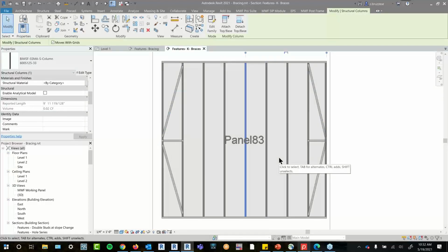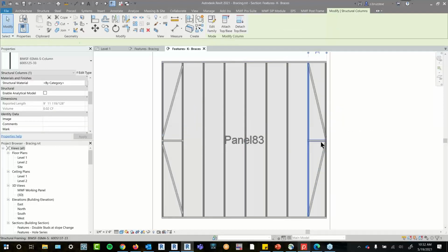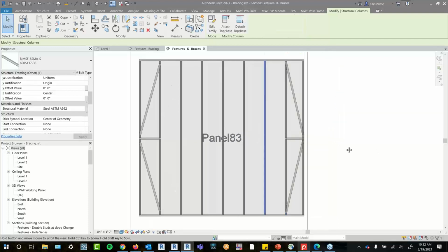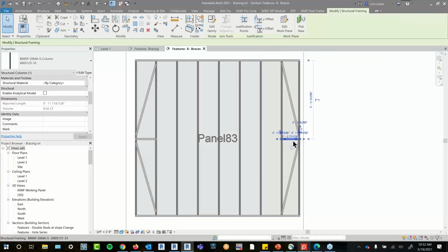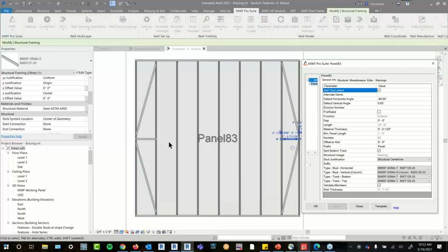So you don't have to repeat it X number of times. You can just add it as different types, basically, and choose your bays that you need to add the K-bracing to. Besides that, though, last option that I'll just highlight, if you did want to place a continuous horizontal, it's just a question I had in a training last week that, again, I thought was a good one. There isn't the option directly in the K-bracing. We're just placing horizontals between bays when you're adding it like this.